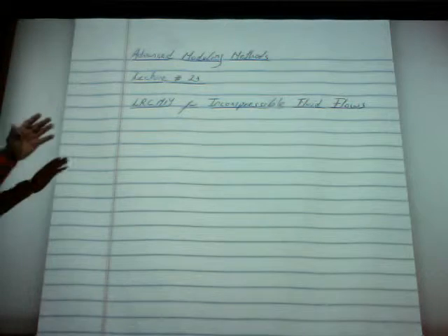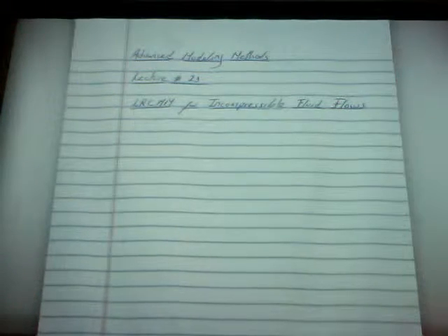So you can take a flow of air and assume the flow behaves as an incompressible fluid because it satisfies some conditions, normally having to do with the Mach number. Okay, normally when a fluid flows under Mach number 0.3, under 30% of the speed of sound, the fluid behaves as an incompressible fluid. It behaves as such. So we're talking about incompressible fluid flows, which, as I'm saying, can mean, well, flow of air, for instance.